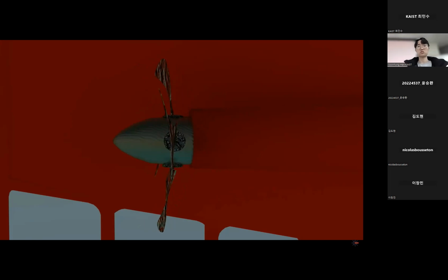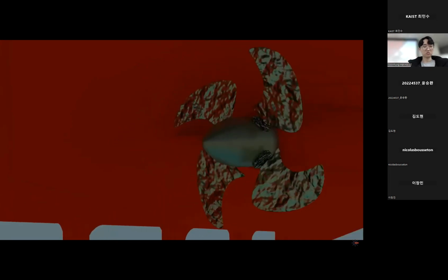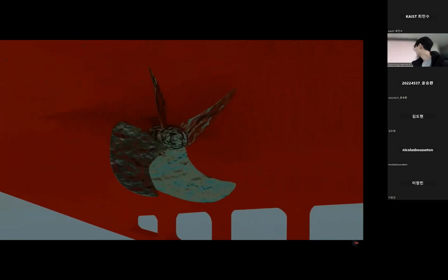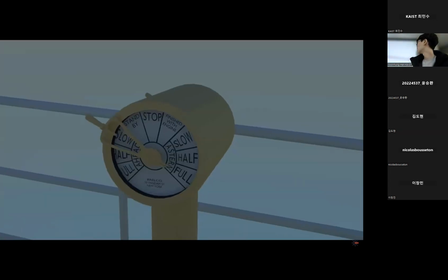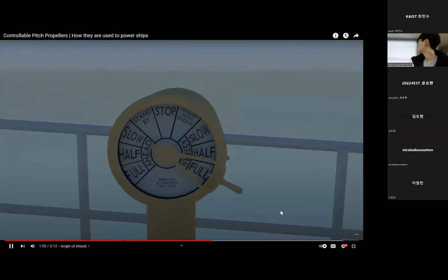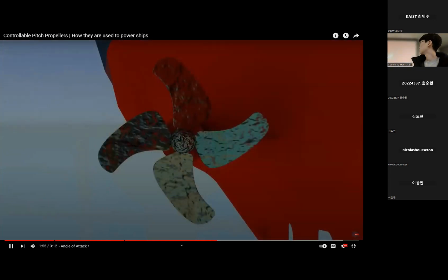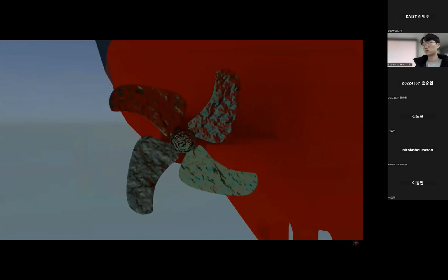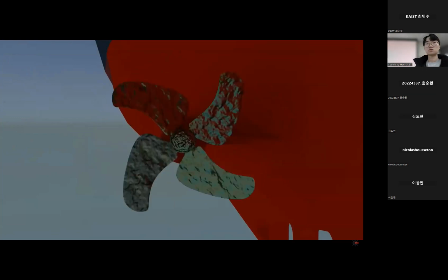For example, this setting would be used when a ship has started her engines but is still alongside her berth, not yet wanting to move. By contrast, to set a fixed pitch propeller to generate zero thrust, you literally stop it. For stern propulsion, a fixed pitch propeller needs to turn in the opposite direction. Ships do this either through a gearbox arrangement or sometimes by literally stopping the engine and restarting it in the other direction.